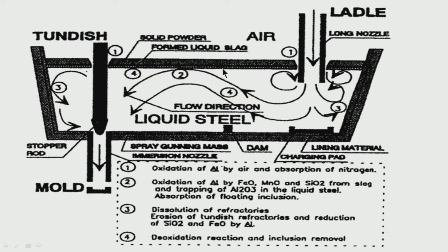One, just at the top of the liquid steel we have a basic slag which is used for absorbing the alumina oxides which are forming and trying to get up and come to the top, and on top of the basic slag we have another constituent of slag which is known as rice husk. It is a good insulator, it does not allow the liquid steel temperature to fall beyond certain limits.